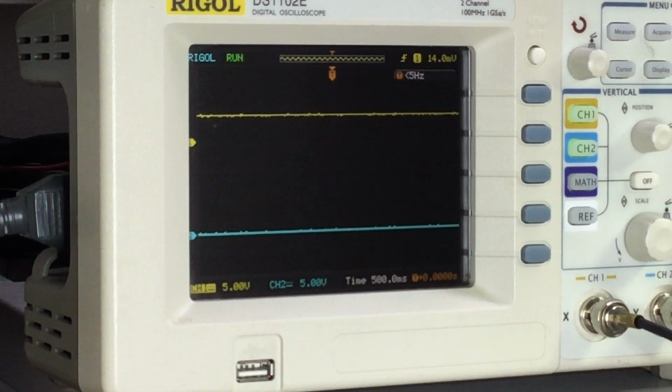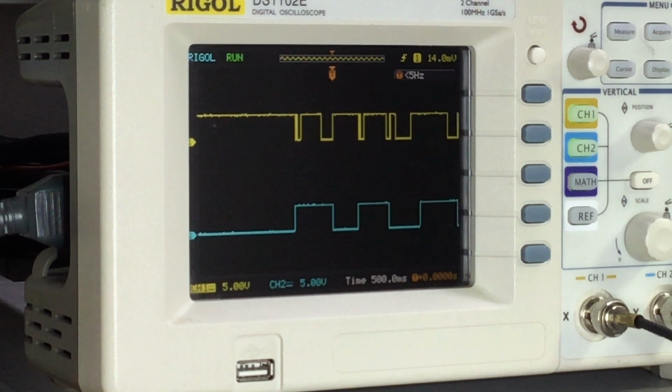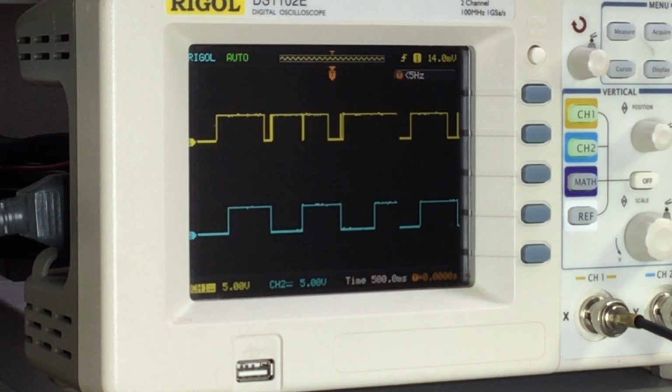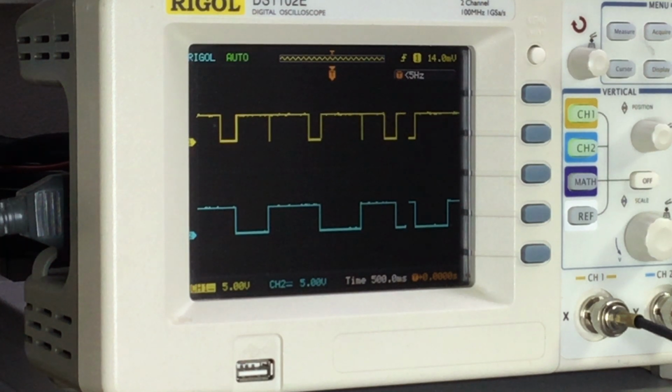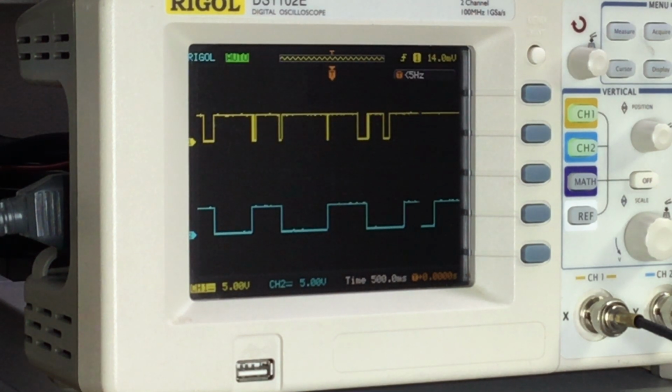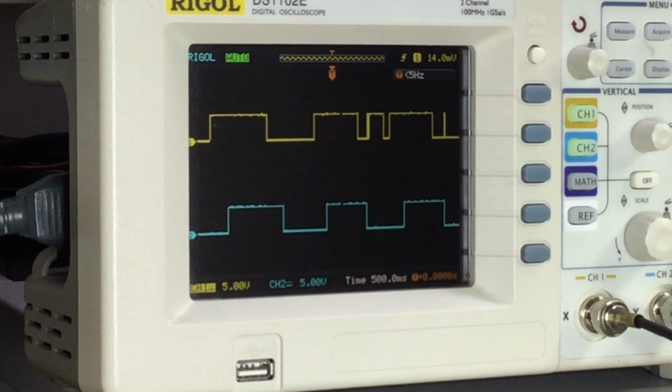So, right, keep turning. 1, 2, 3, 4, 5, 6, 7. So you can see the frequency of the bottom waveform is more or less identical and uniform in mark space ratios. I'm turning the control and it's basically noise free, whereas the top trace is one of the Hall effect sensors,